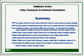When this rendering method is used, the subdivision value needs to be set really high, and for a good quality noiseless image, it needs to be set so high that you have at least 1,000 sample rays for every rendered pixel. Also remember to disable anti-aliasing when using this option.